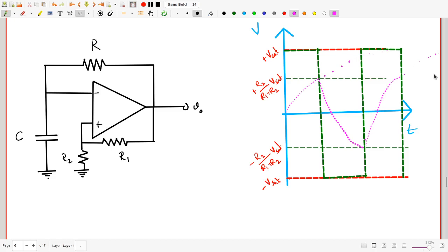So as you can see, we have made an oscillator with just an op-amp and a few circuit components. A very, very cheap oscillator which is actually quite a good and stable one. You can use it for many practical purposes. Okay, what will the time period of the oscillator be like? Well, I will allow you to calculate it for yourself, just as a standard RC circuit charging and discharging calculation.